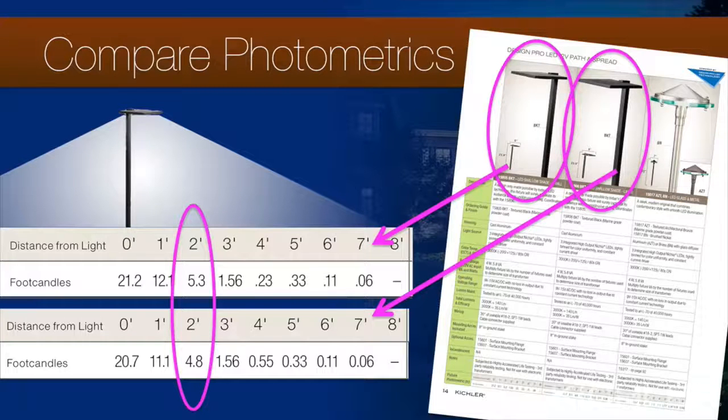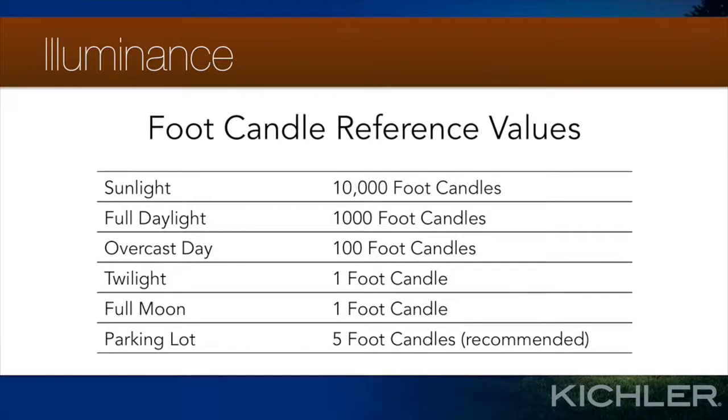In this case, the difference is small, but when sizing fixtures, you can save yourself the trouble of having to substitute a different fixture post-installation by ensuring that the fixtures you specify produce the right number of foot candles for the application. A foot candle is somewhat of an abstract term. To get a sense of what it means, let's have a look at some foot candle referenced values.